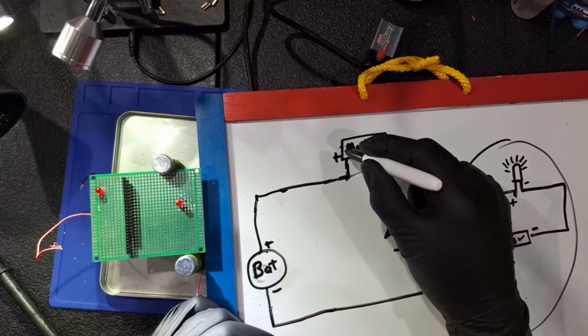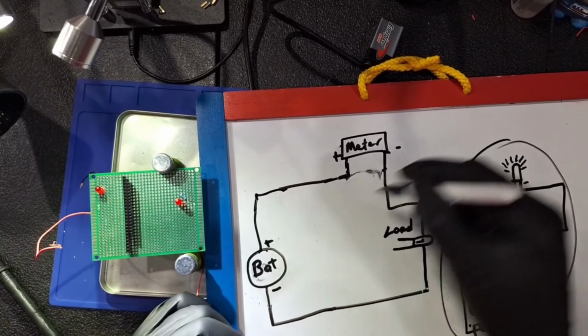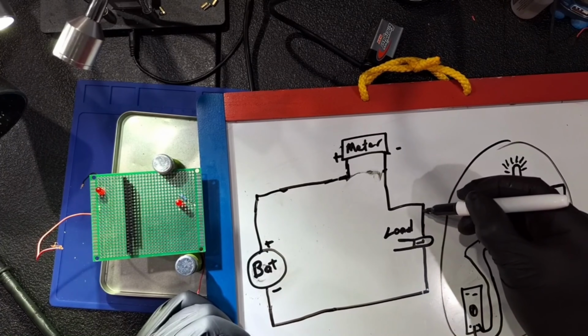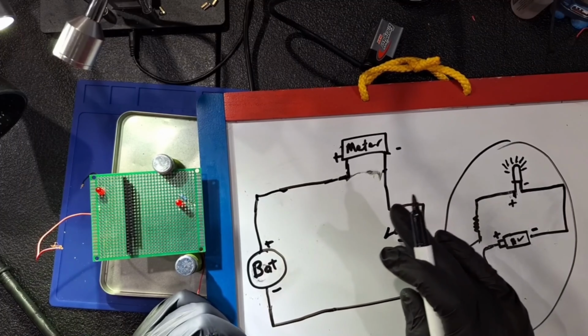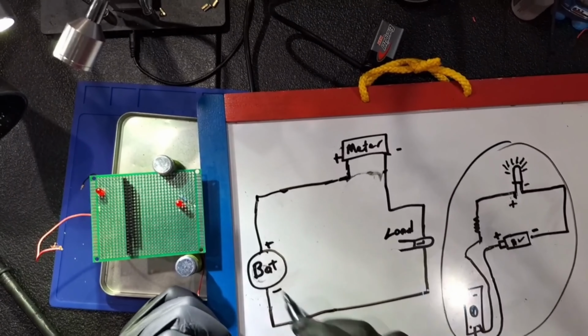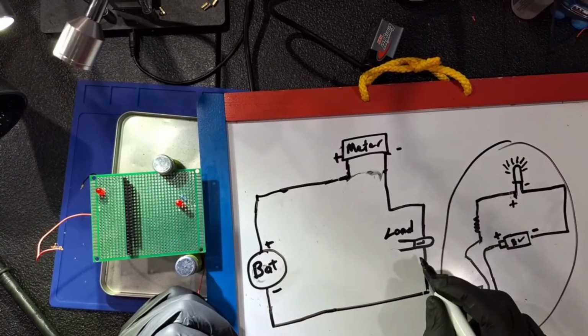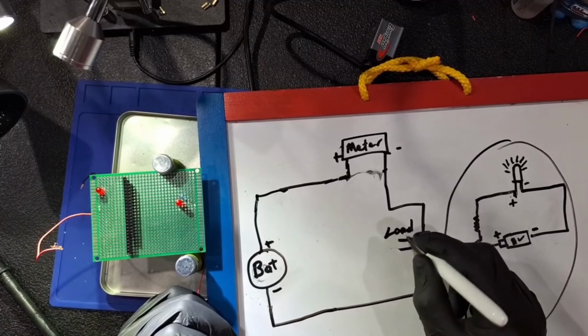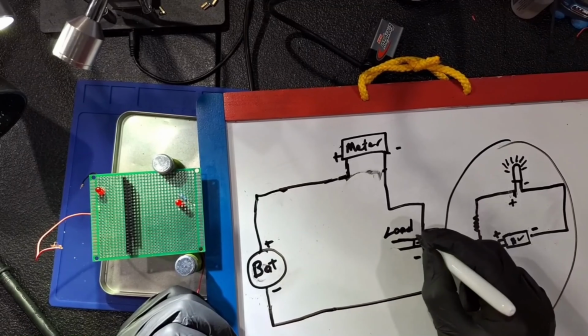But on the LED in that diagram, the side that the multimeter goes to is actually the positive of the LED, because if you look on the other side of the battery where it's a minus, the minus goes all the way back to the LED negative leg, right? So this is how it should be.